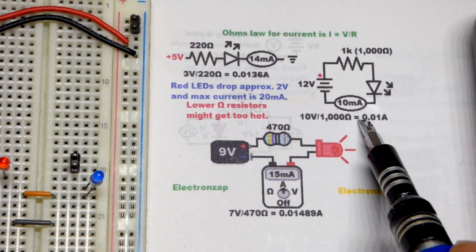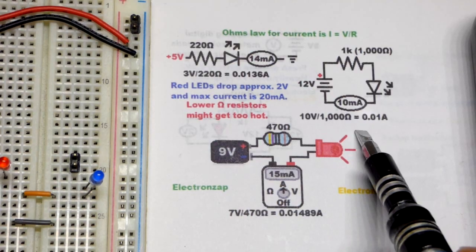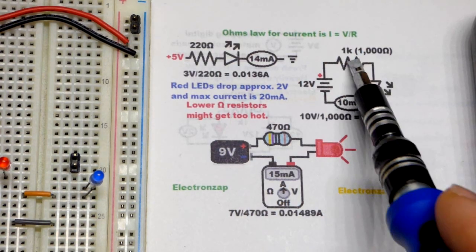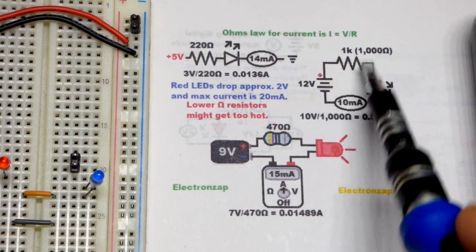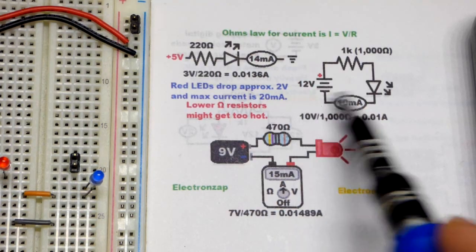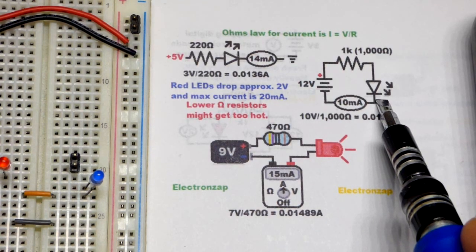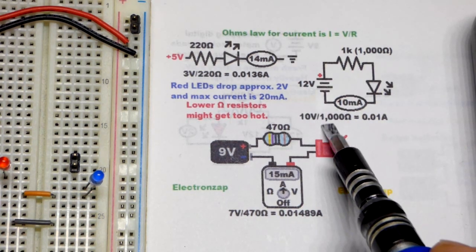So, practice these simple ones first. When it comes to the math, this one, you can just do mental math. Really easy. Each volt across it is 1 milliamp of current. So you just set whatever voltage across it you want. Normally, though, you're working with a fixed voltage, and then you're going to be dropping some voltage, and so that gives you the amount of voltage across the resistor.